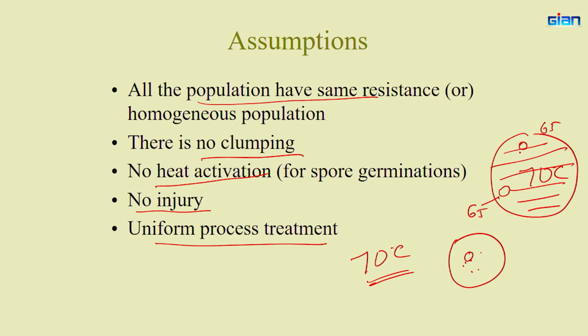The bacteria in these locations can survive, then it creates a problem. So if the entire section is 70, it's okay, you can have some region at 75 Celsius or a much higher temperature, but you don't want anything less than 70 Celsius. So you're always going to process at the appropriate temperature or a little bit higher so that you deliver your heat treatment.